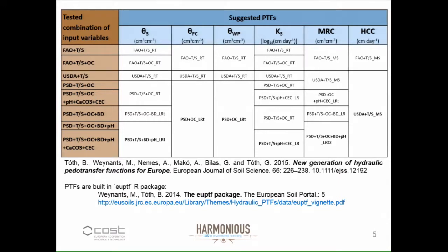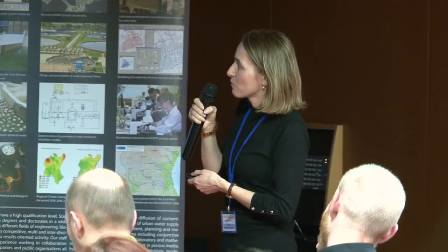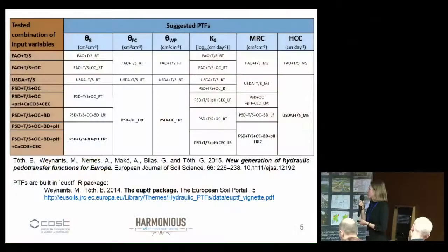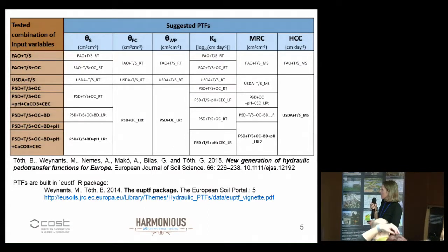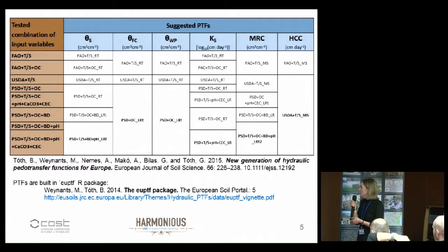And what you can see from here is that, for example, for the saturated water content, the pH was found important, which is new because before, for soils from Europe, it was not found important. It was like that Tomasella and Hodnett analyzed the soils from South America, and they found that it is important. And then it came out that yes, pH is also important in this case. Okay, maybe if we had information on structure, if we could have used it, maybe pH would not be here, but then it helps.